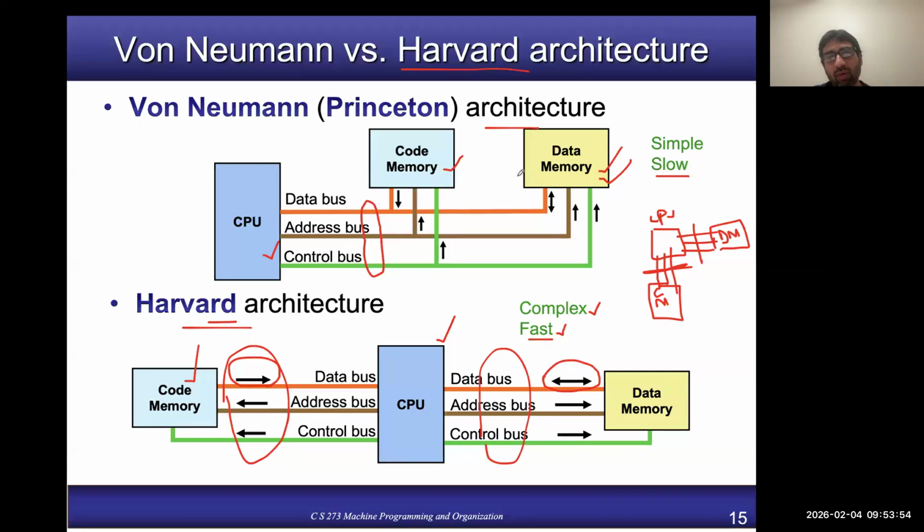So you have the CPU, you have two different chips to hold data and memory, but you use a single set of buses to communicate with both. So it keeps the pin count low, right? At least it reduces the pin count by two. Here, if you needed six in total, here you need three, right? One thing. And second thing is, since the communication is slow, we don't want to create more communication bottleneck by creating more buses.